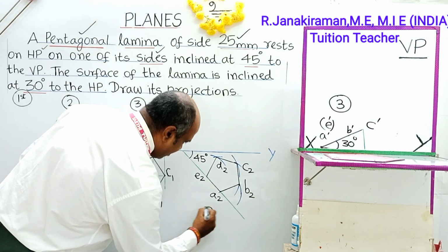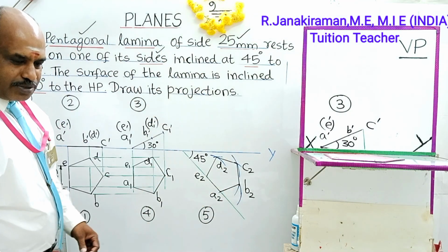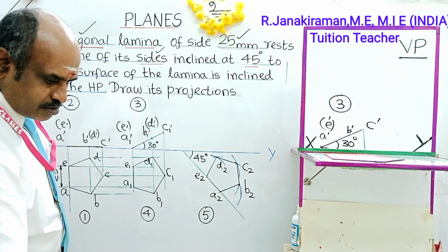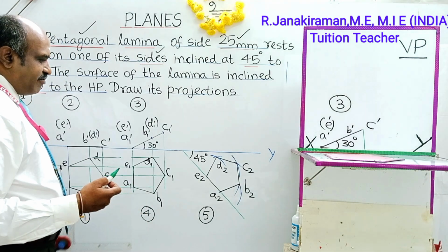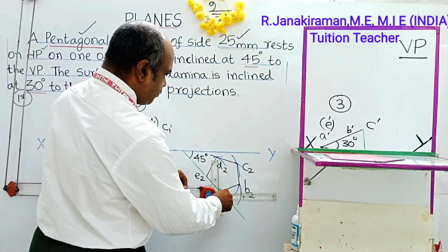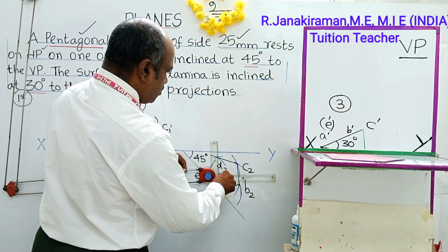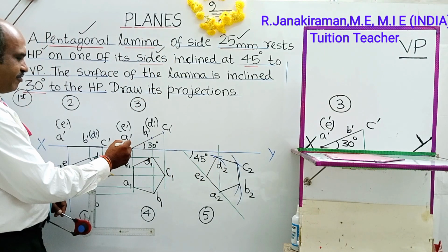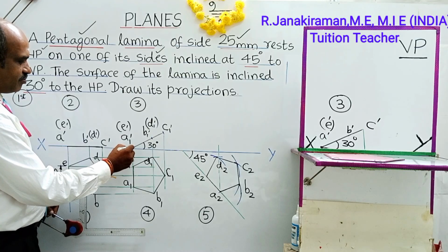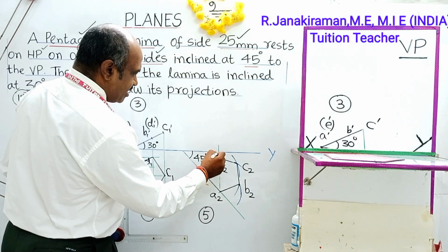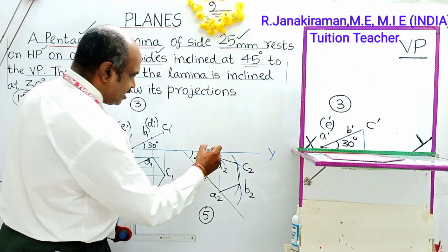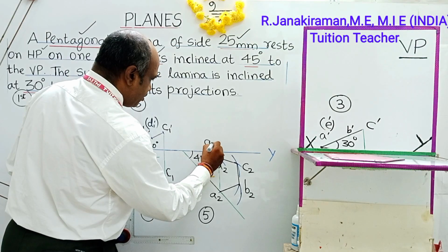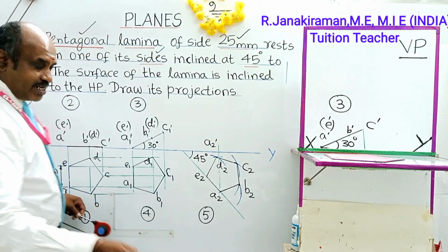Next, we go for final front view. So take 2H pencil. Draw vertical projector from A2. Horizontal projection line from previous front view. This is A. Both A intersect at A. This point of intersection shall be marked as A2 dash. Front view means a letter with a dash will come.